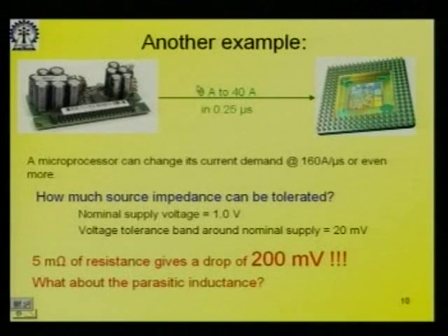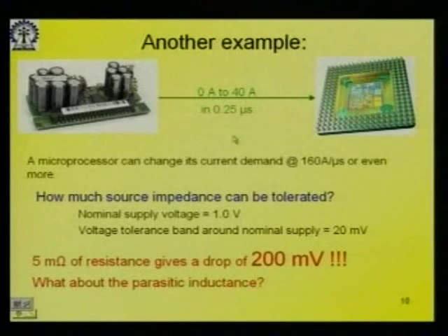And secondly, how you connect these two is also important. You may not always have a purely resistive connection. Even a simple single wire at frequencies like this will act like an inductor. It will have a so-called parasitic inductance. That will reduce the voltage further,